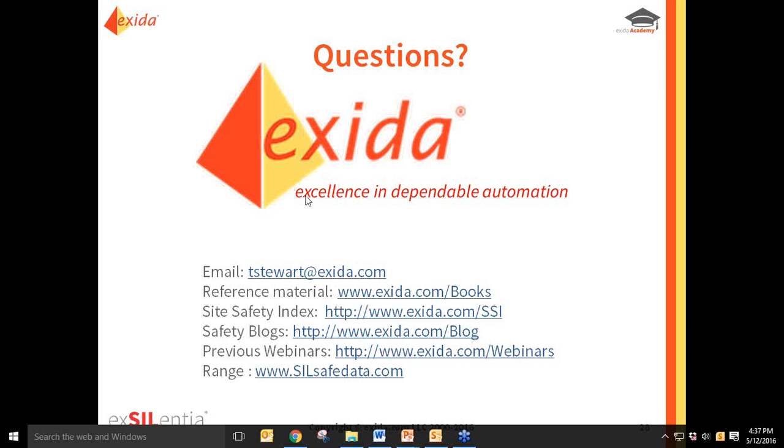And then finally, the last question I have here: specifically, what types of failure data are required for this tool? If you want validated field failure data, you're going to want to record any type of failure, whether it's systematic, whether it's random, whether it's even, hey, we painted this product the wrong color. You want to record everything. The more information you record, the more statistics, the more analysis you can do on that product. So it's not really what types of failure data you need for this tool. It's everything.